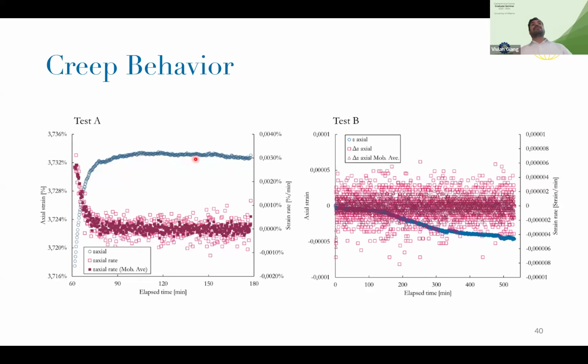And there is something called the third stage creep, in which this creep begins to increase. So there is an initial deformation, then a little deformation over time, and there is a moment when the sample cannot stand more under isotropic loading and begins to deform again.